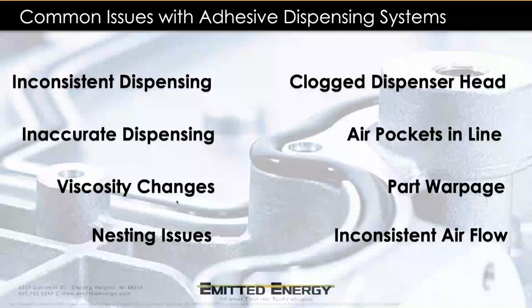Viscosity, we want to heat this material up to a certain temperature, and depending on your material, you have different parameters, of course, of what temperature that adhesive needs to be to properly be dispensed. And when there's variation in the line, now you could have plant variation, you could have ambient temperature variation. There's a lot of things that can change over time. You could actually have a problem in the heater system that you wouldn't know about until you do the leak testing, and you have to throw out those parts. So there's a lot of issues with viscosity.